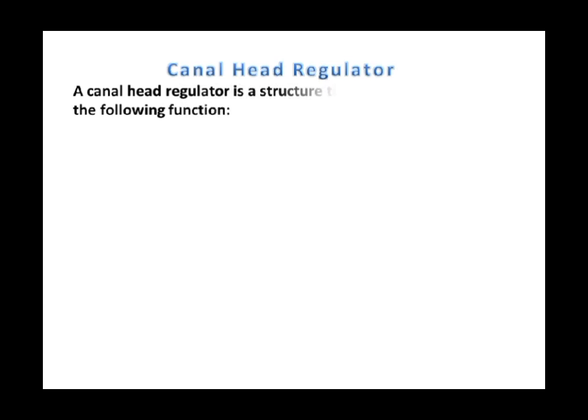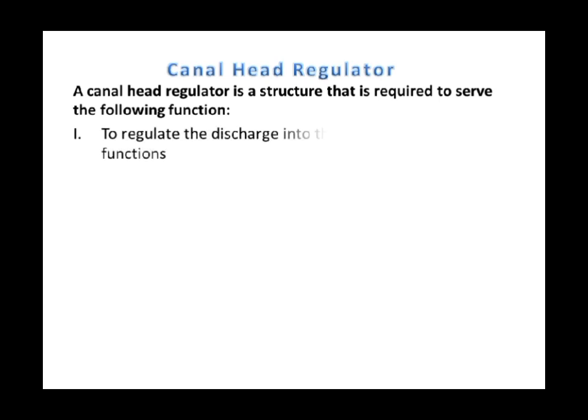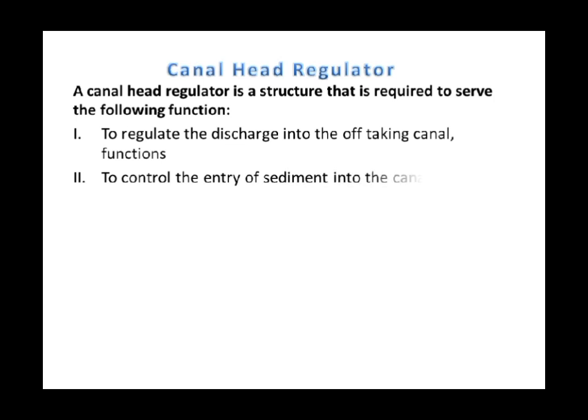A canal head regulator is a structure that is required to serve the following functions. 1. To regulate the discharge into the off-taking canal. 2. To control the entry of sediment into the canal.